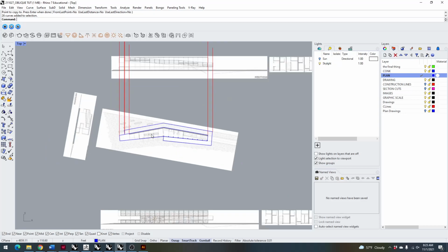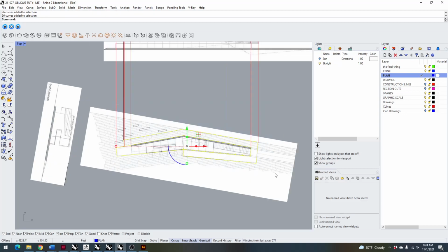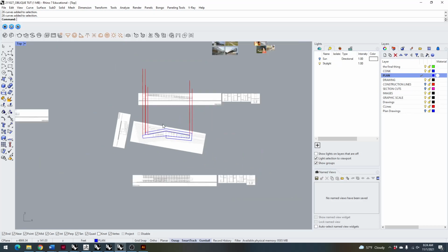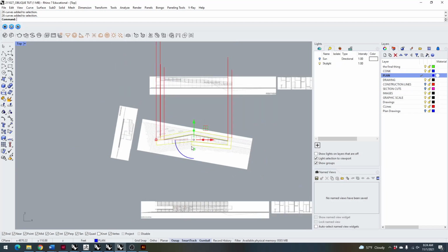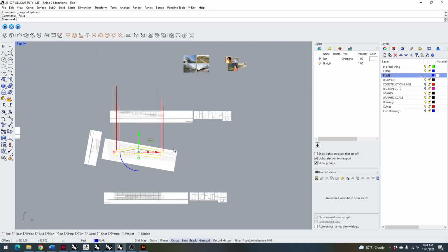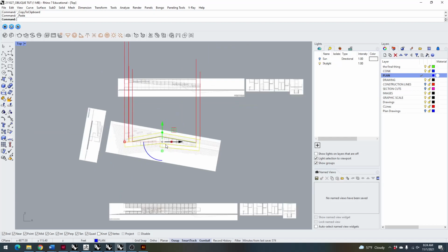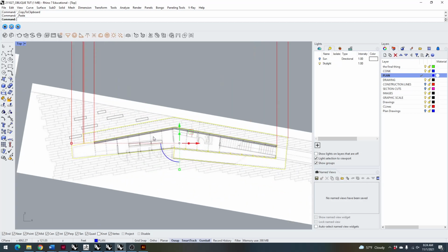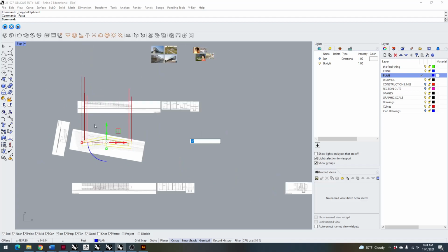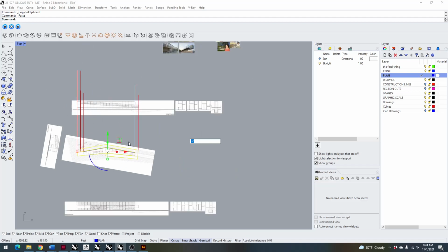So the next step in constructing our oblique, and this is when it, I guess, gets a little spicy or interesting, is we'll take our traced plan and we'll copy and paste it, and then we'll move it off to the side. But I would recommend that we move it over by some known dimension, because this is a true scaled set of drawings.